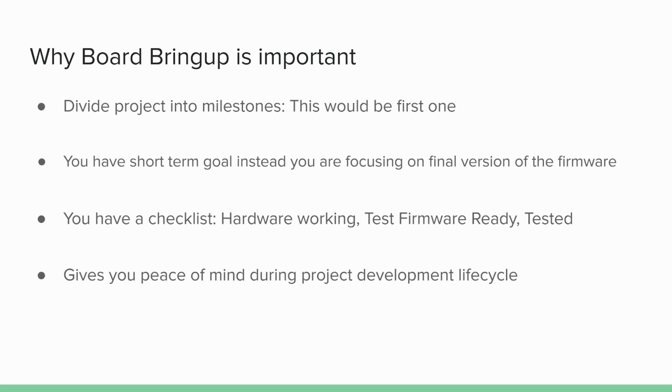This is very important. We struggle a lot sometimes when we don't know the problem. Is it the hardware giving us an issue, or is it the firmware? During development, if you are stuck, which happens normally, the reason could be like, yes, it was working just this morning and now it is not. What you can do in that case is load your test firmware to ensure that all the peripherals are still working and passing the test. If the test is passing, then debug your application. If it is not, then troubleshoot your hardware. Something has gone wrong, so this gives us a direction on which way we need to troubleshoot.